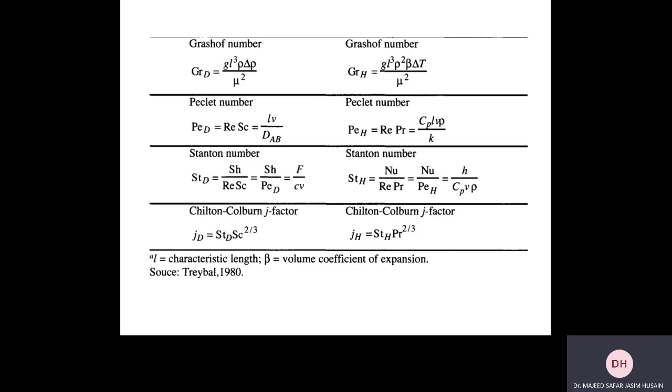And the Prandtl number will be replaced with the Schmidt number, and the power stays the same. It didn't change. So 2/3 stays 2/3 there. So you can now try to understand what's happening. Using dimensionless groups, we managed to change from heat transfer to mass transfer. So this is our target.